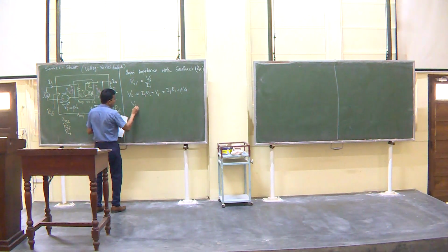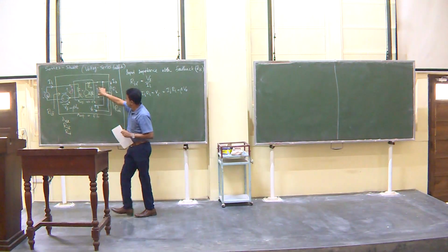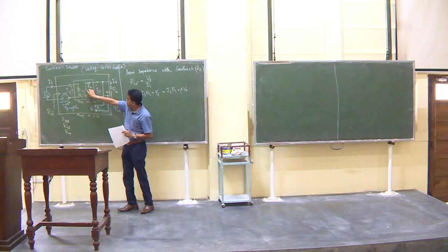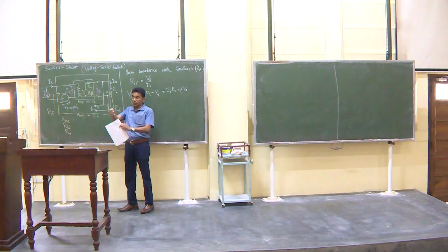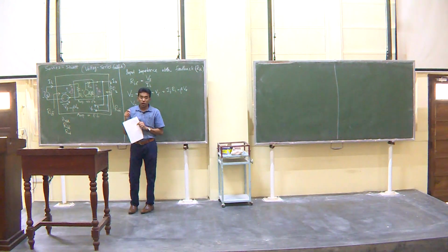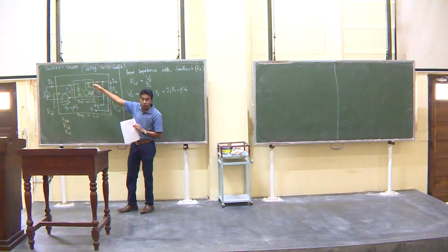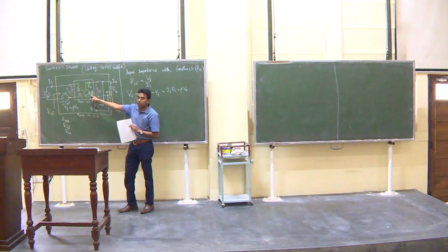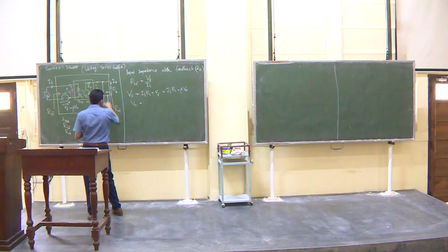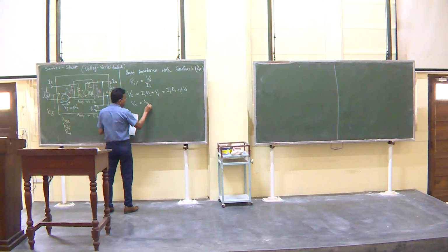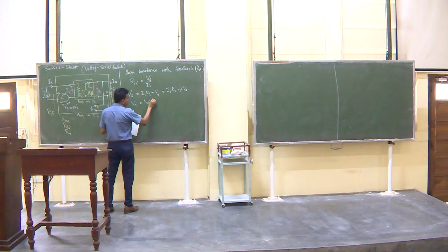But V out is equal to this voltage here, that is equal to this voltage minus the voltage drop across that resistor when there is a current drawn. If you do not have a load, that will be the open circuit voltage, that will be equal to AV times Vi, right. But now it is connected, so let us write that as AV times Vi.